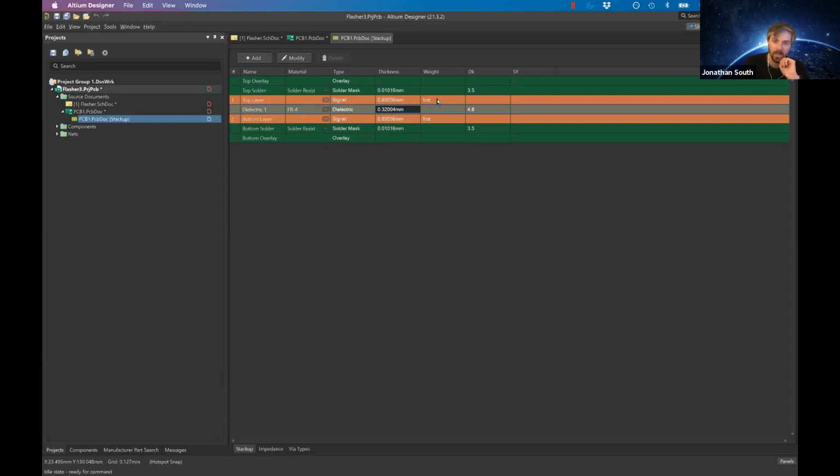You can select the weight, which is basically the thickness of the copper layer that goes on it. So obviously the higher the weight, the thicker it is and the more current and power those traces can handle, and the lower resistance they have. So that can come into design consideration when you're making a quote unquote proper circuit. So we're going to stick with the default here.